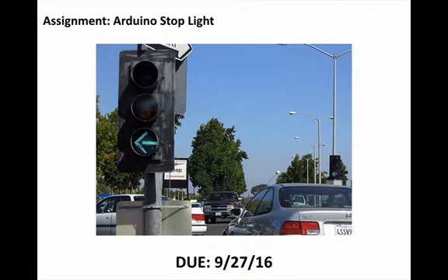I have shown in class, and we'll post on the website after this is due, a basic state machine and how you could implement it in C. So you should use something like that. It should be functionalized, and it should be well documented, and it needs to actually do the job right, and it needs to have a shutdown state. When you're looking up the switch statement, you should see a default. So you could have switch, multiple cases, and then default, and that would be something bad has happened. Let's go to shutdown.